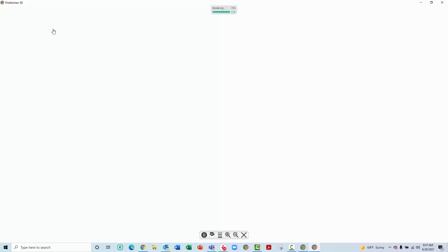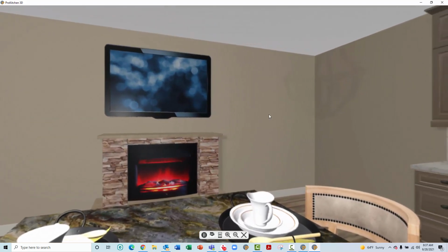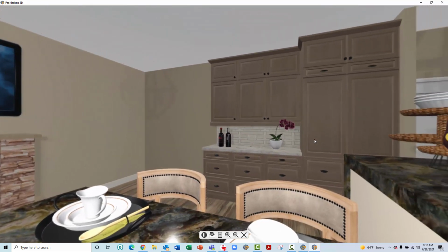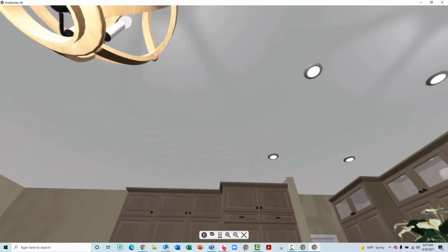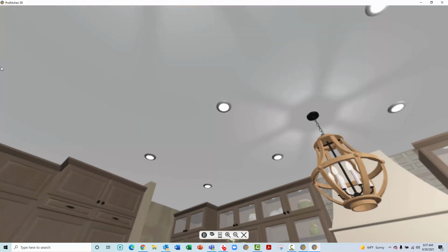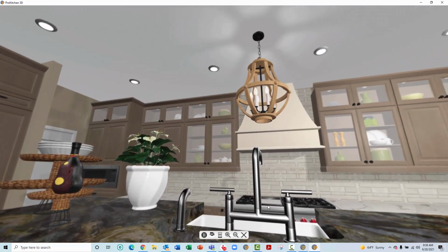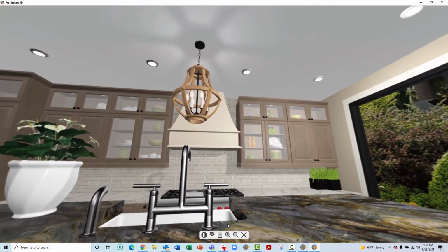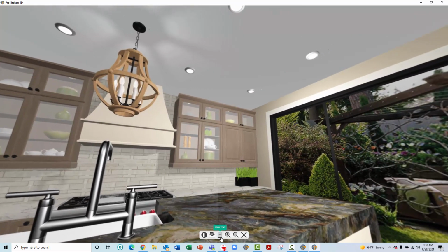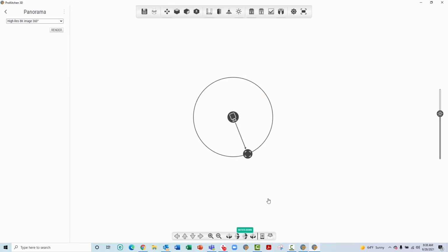Once the panorama is finished rendering, you can zoom in and out, as well as right-click and hold to navigate manually at the bottom of the 360 panorama video. You can pause or play, zoom in or zoom out, send via SMS or email, and close the 360 panorama viewer with the X. Once the viewer has been closed, left-click the over arrow at the top left corner of the sidebar to exit.